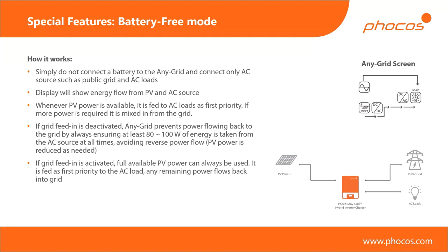And in this case, we have a very special topology for this unit, which actually allows functioning without a battery. So again, I very strongly recommend that if you work without a battery, you do have an AC source, so typically a grid. But theoretically, again, even if you don't, what will happen is it will try to balance the PV power against the AC output power.